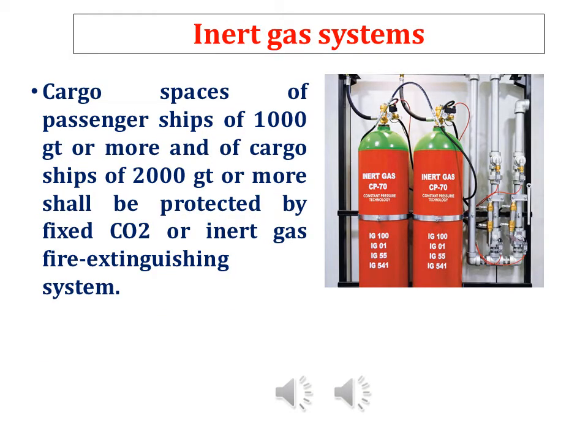Inert gas systems. Cargo spaces of passenger ships of 1,000 GT or more and of cargo ships of 2,000 GT or more shall be protected by fixed CO2 or inert gas fire extinguishing system.